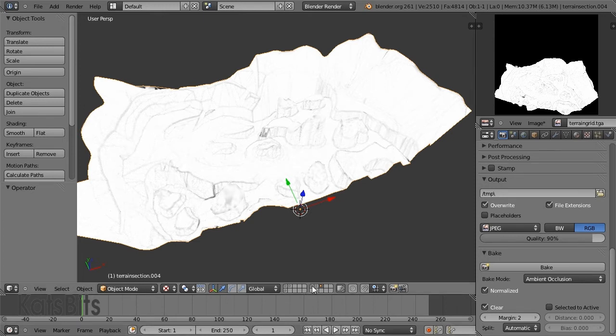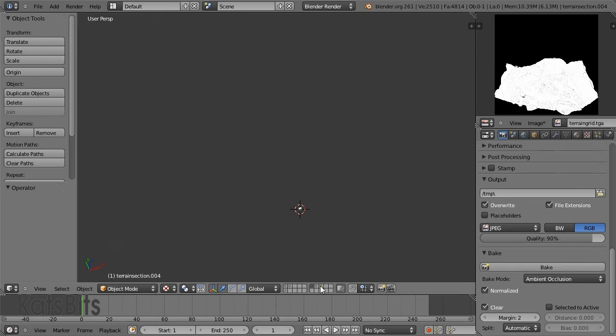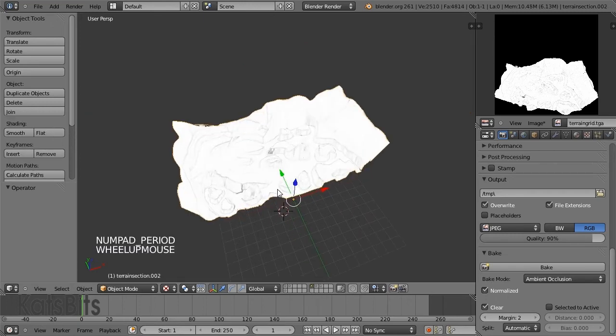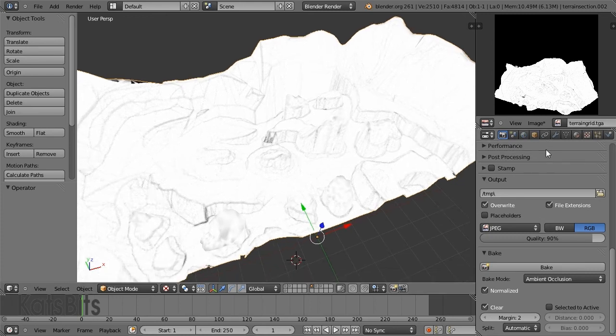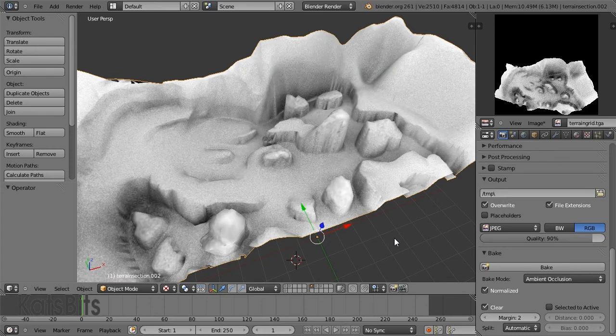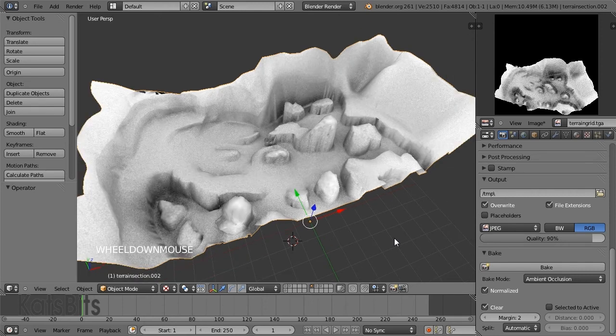So always make sure, you can see how big that is. That's the tiny teeny one relative to Blender's scale, and this is a mesh the size it would be if we were using it for something. So select that and rebake. Instantly notice the difference. The bake results depend on the size of the mesh, so keep that in mind as you bake your terrain. Particularly because terrains usually are quite large objects.